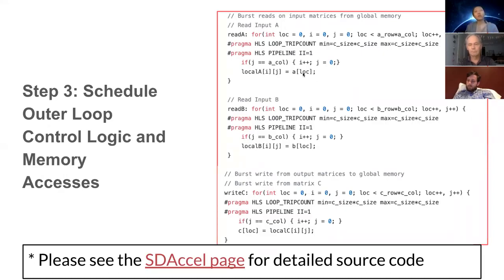A very good thing about this is that we can put this A as a port, as an input to this accelerator function, and later we can synthesize this port. We can add a pragma saying this port will be implemented in AXI, so that it will generate the AXI protocol for you. Once you do this loading data from A loc to the local A, the high-level synthesis compiler will compile this down to specific AXI requests that need to happen at a certain time. That simplifies the interface generation a lot, because a lot of times bugs come from how you specify the signals for the interfaces. So that's one very significant advantage of high-level synthesis.